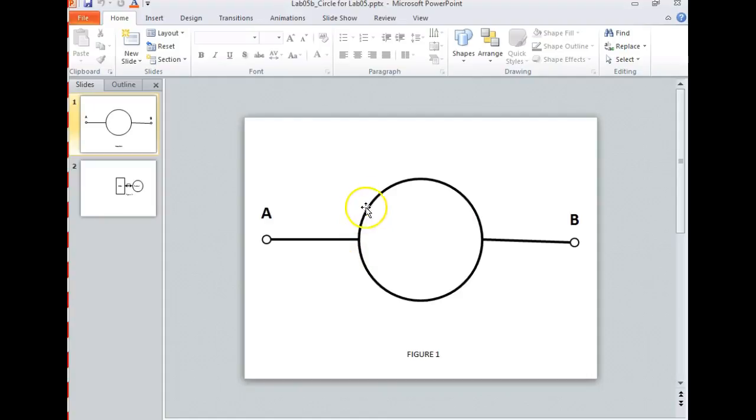And we'll see what happens, and we'll play around with this because what will probably happen on some robots is it'll actually stop at the midpoint, and then it'll continue on. So if it stops, it's no problem. Then we'll come back and we'll modify the program and just change the round off a little on those points to make it do what? Make it move nice and smooth.